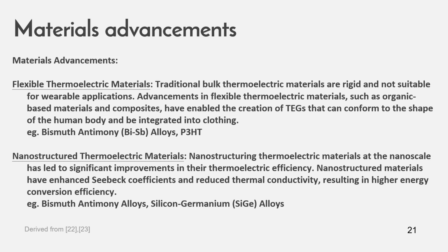And coming on to the advancements made in this field, and first of all we'll see the material advancements. And first is the flexible thermoelectric materials. Traditional bulk thermoelectric materials are rigid and not suitable for wearable applications, and advancements in flexible thermoelectric materials such as organic based materials and composites have enabled the creation of TGs that can conform to the shape of the human body and can be integrated into clothing. Some of the examples are bismuth antimony alloys and P3HT. It's an organic compound.